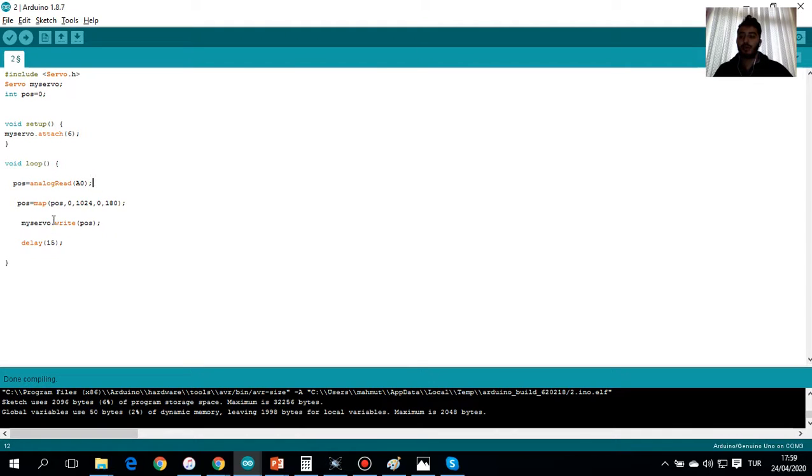As I already told you, the analog signal is stored in 10 bits, and 10 bit starts from 0 and goes to 1024, but my position has to be between 0 and 118. That's exactly why I have to convert that 10-bit value to 0 to 118, and that's why I've got specific code here.